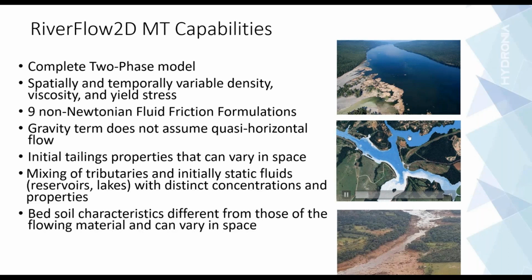So you can see here, this is from the Brumadinho simulation. You have the tailings, represented at this dark concentration, and then you have a river downstream, and you can see how the mixing occurs and how the model computes the mixing of different concentration tributaries.